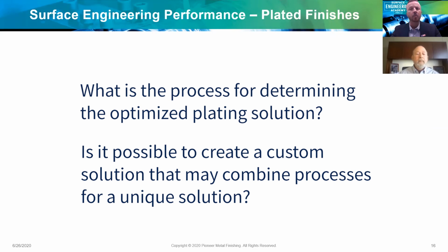We see the different co-deposits, whether those are Electroless Nickel. Certainly PVD offers that level of flexibility as well, whether it be additives for lubricity, for hardness, or different chemical properties for corrosion resistance. So you definitely gain more flexibility in the more modern engineered coatings such as PVD. But of course, there's a cost factor to be shared there as well.